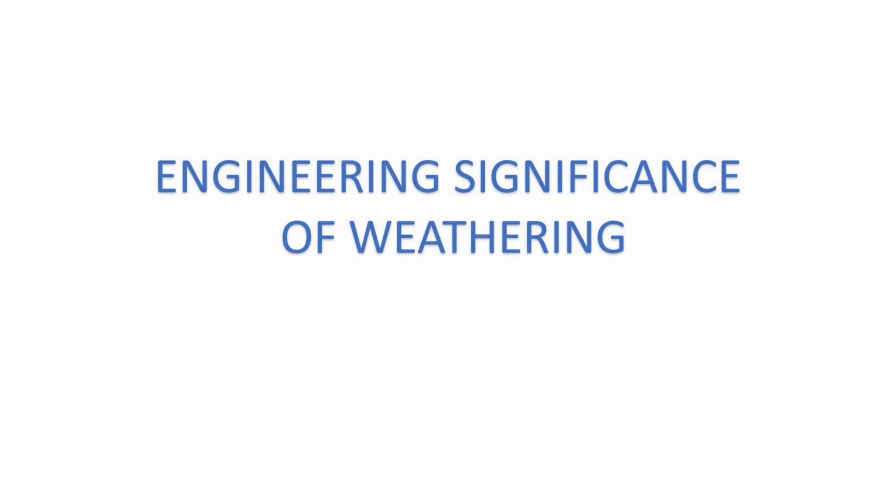Moreover, weathering also brings instability in slopes due to chemical action which breaks the bonds between rocks. When bonds between minerals are weakened or removed, the slope rocks lose shearing strength and become prone to failure.